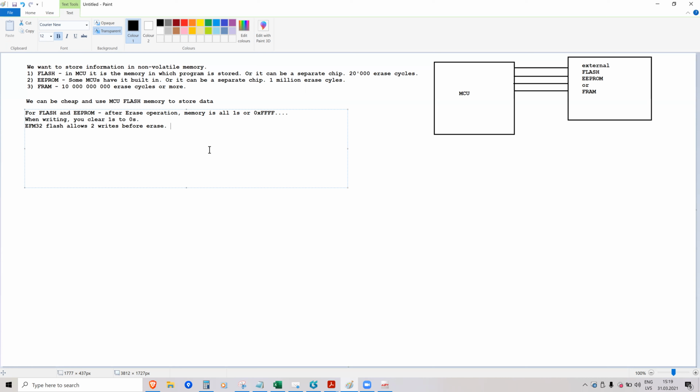So to save flash, we need to implement some kind of wear leveling. Instead of erasing data every time we want to write new data, the sectors are marked as old or used, but they are not erased immediately. First, other free sectors are used, and when there's no more free sector, then all of them are erased, because erasing takes time, and we don't want to slow down our computer every time we run out of free sectors.